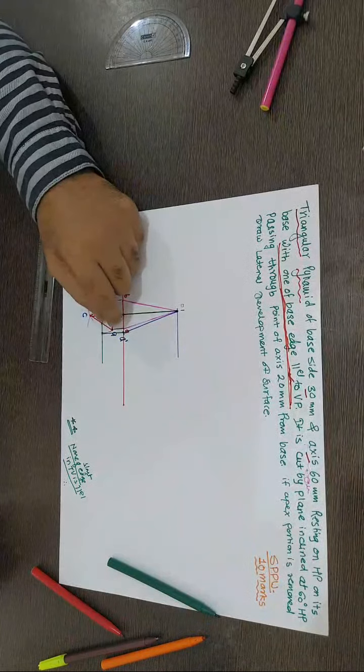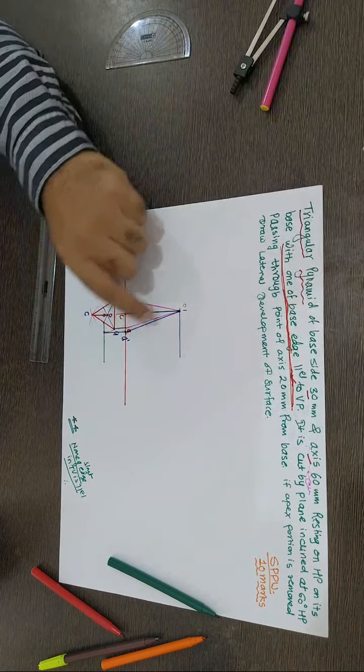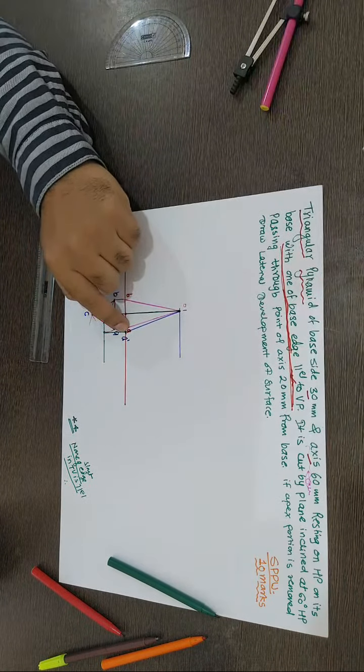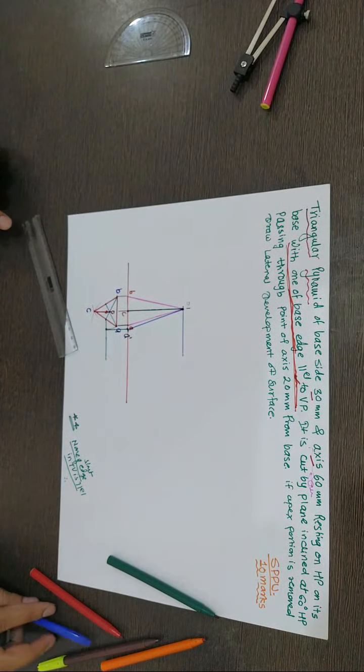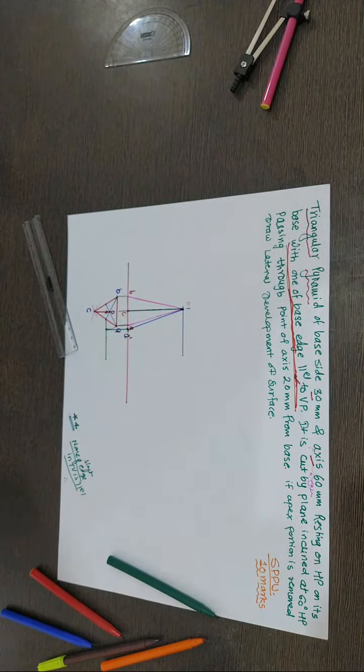So we make this side edge parallel, we project here, join with the same apex, this represent the true length. Then you follow the same procedure. I hope you are following me. If any doubt, if you left behind, let me know in the chat.